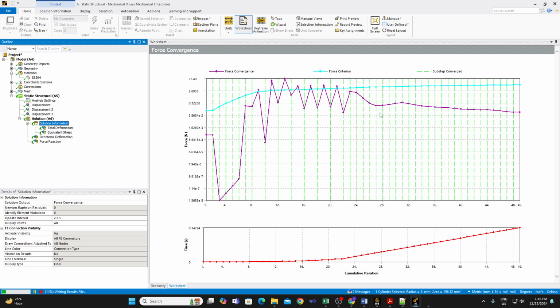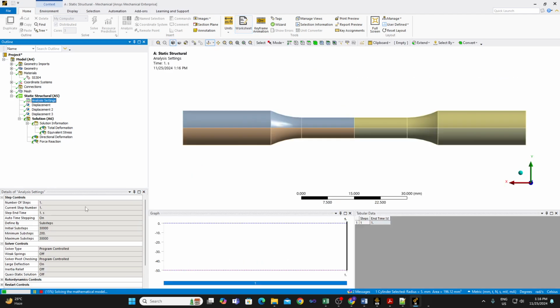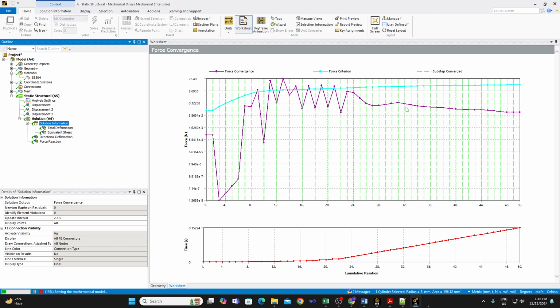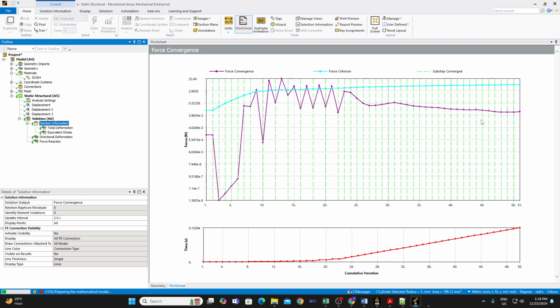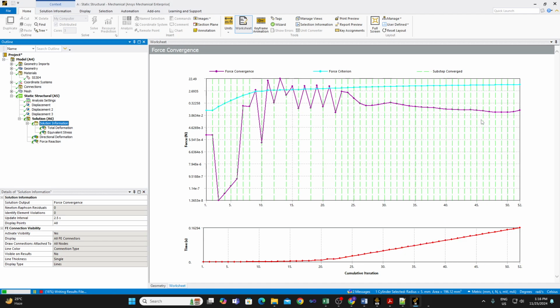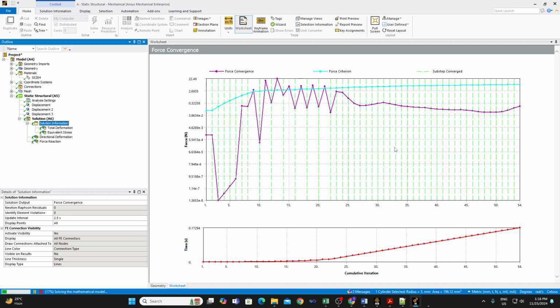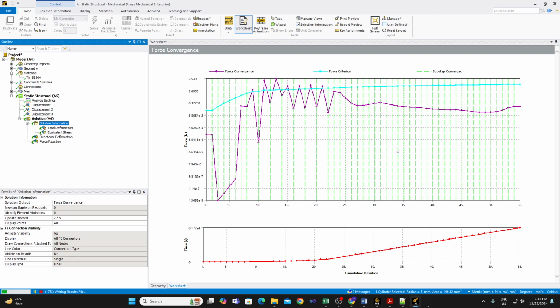Once again, the minimum number of time steps that you have taken is 200, and it might seem like that is an overkill, because the convergence is happening practically at each iteration. So iteration number and the number of substeps are essentially the same. But if you pay a little attention, you'd realize that the specimen is about to elongate more than 100%, which means each of these substeps is resolving more than 0.5% of strain. That is 5 into 10 to the power minus 3 strain. That is quite huge, even for plastic strain. So we are mostly on par with the necessary number of substeps.